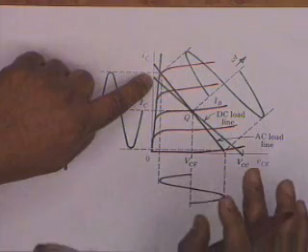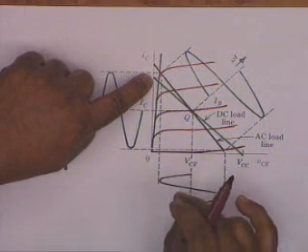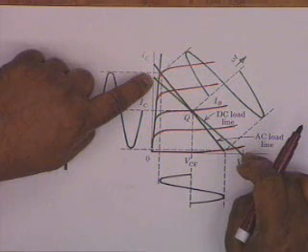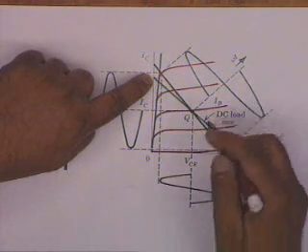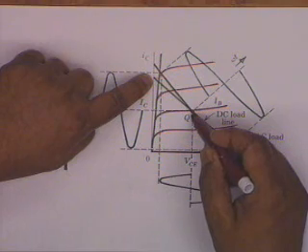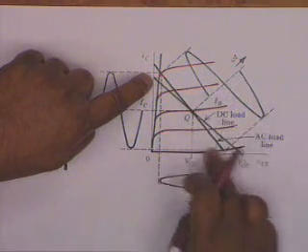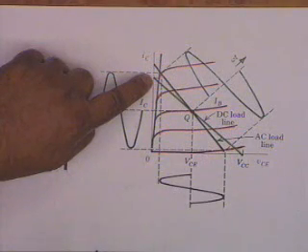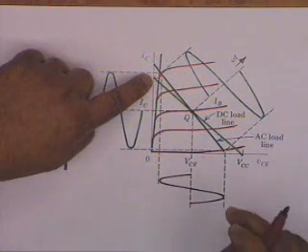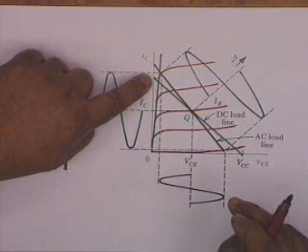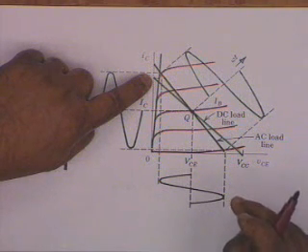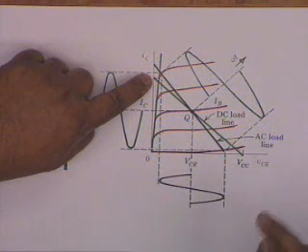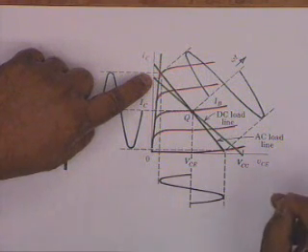And normally, if the DC load was equal to the AC load, then you would like to choose your operating point or the Q point approximately the middle point of this. Isn't that right? So that there are equal voltage swings on both sides and equal current swings on both sides. Okay. The AC load is not RC plus RE, but it is RC parallel RL, and AC load is smaller than the DC load.